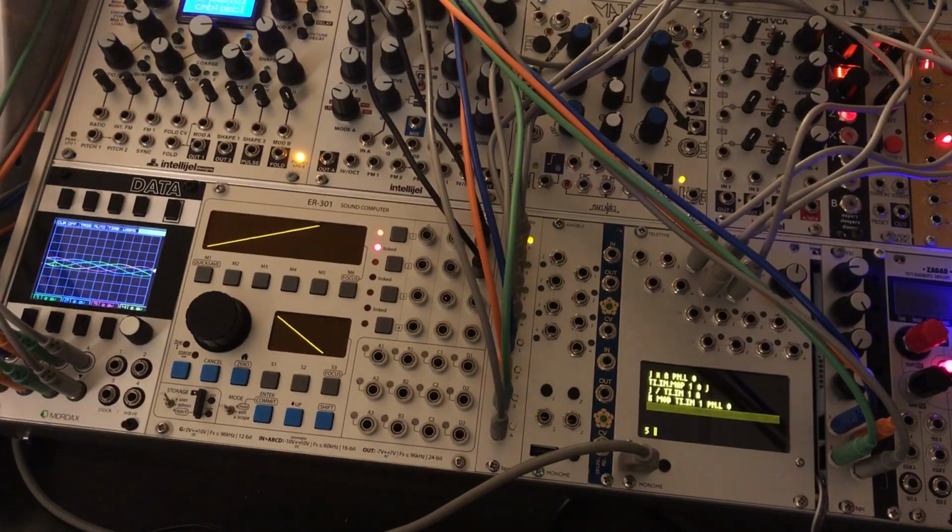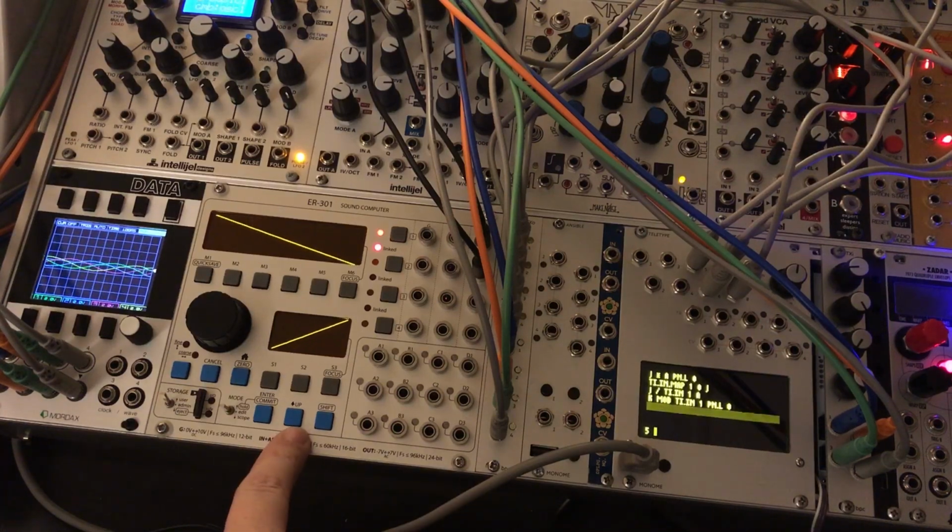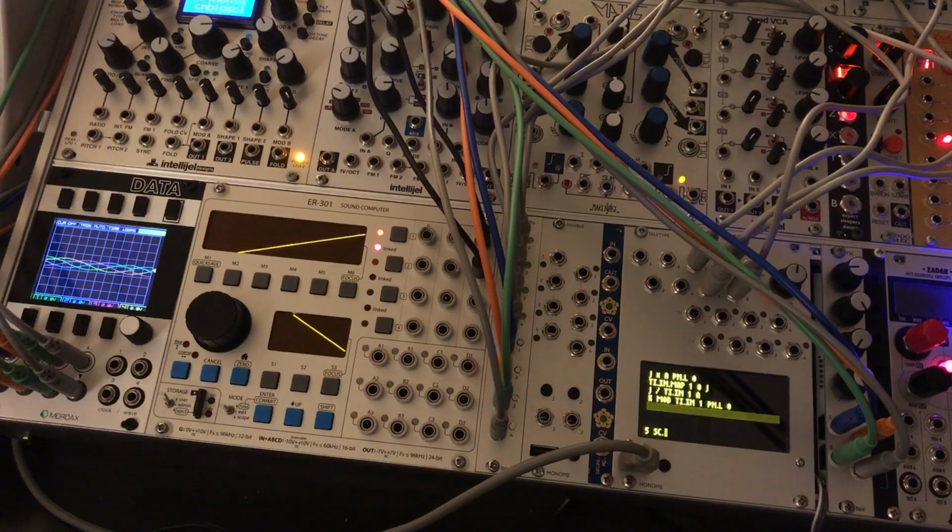And now we actually want to set the note number on our destination. So again, we're going to the ER301 here over the I2C bus. I'm going to do SC. If you're not using an ER301 and you're just using a bunch of other tuned oscillators, you can just leave the SC dot off. So we'll do SC.CV, and we're setting it for number 1 right now, port 1. And what I want to do is add an offset for the octave, and then add the note number that I look up.